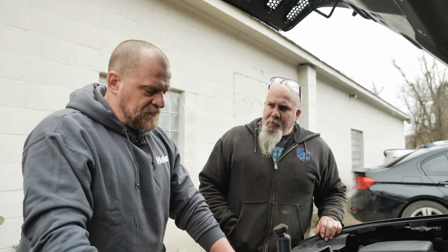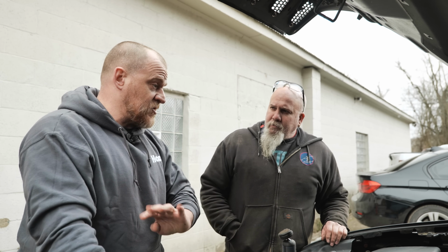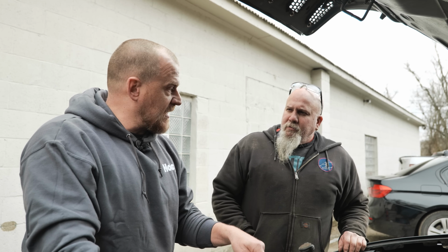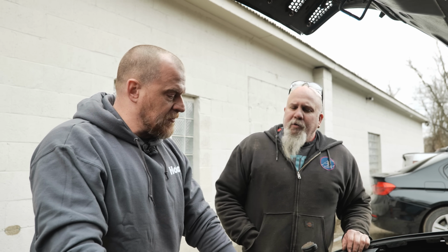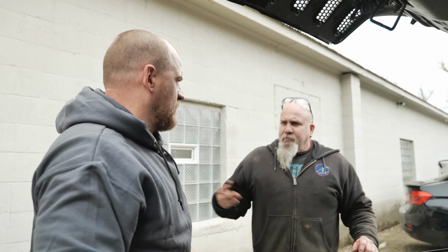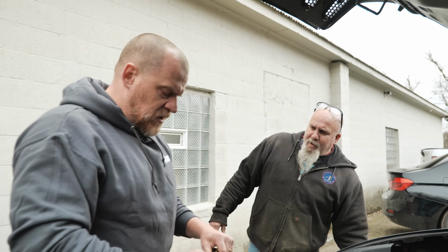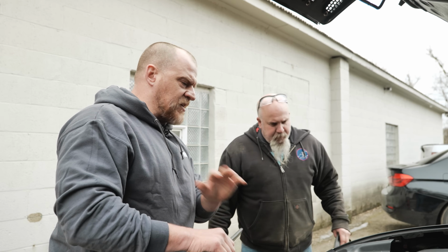I hate rolling the dice, but this is either going to be A, it's already fixed and it's burned itself off, or B, it's going to happen again and it's probably going to be that upstream O2. Okay. At least we know that it's acting up. Change the O2 then, and I'll have you come back. And this is 100% not a vacuum leak. I can tell you that.